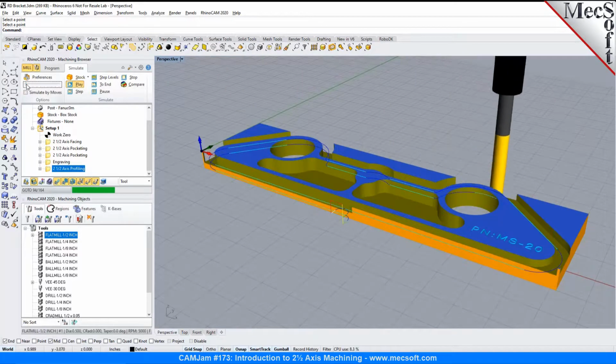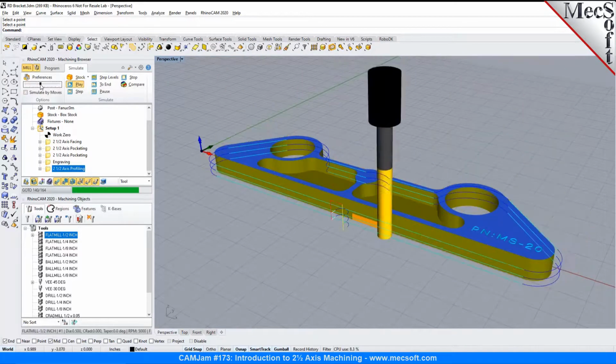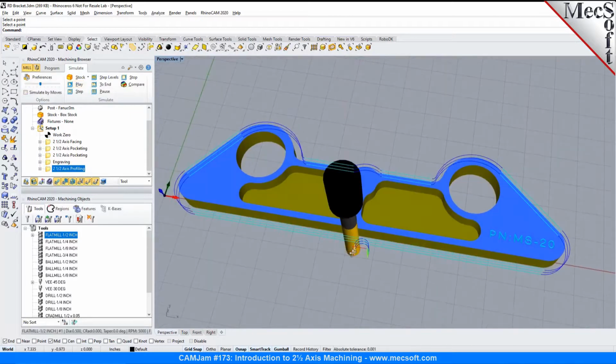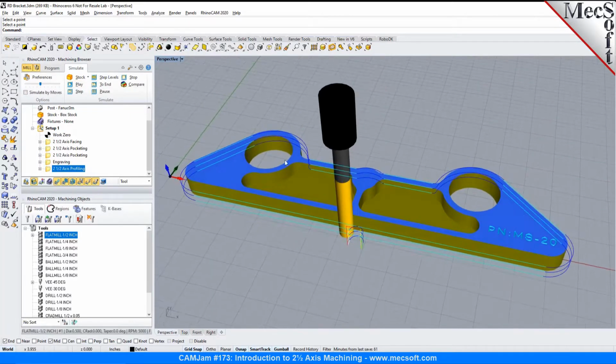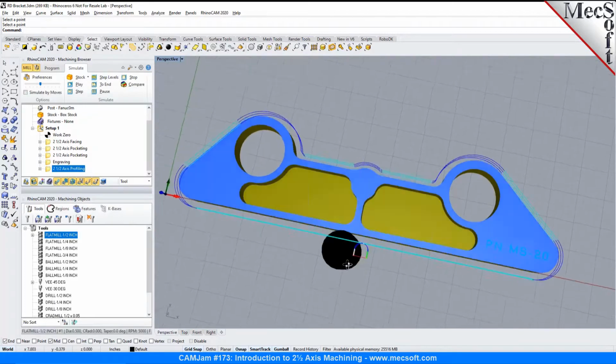And anytime you can control the simulation speed. And as you notice here in the simulation, I've chosen remove remnants during simulation, so it automatically removes the remnants from the stock once the simulation is completed.